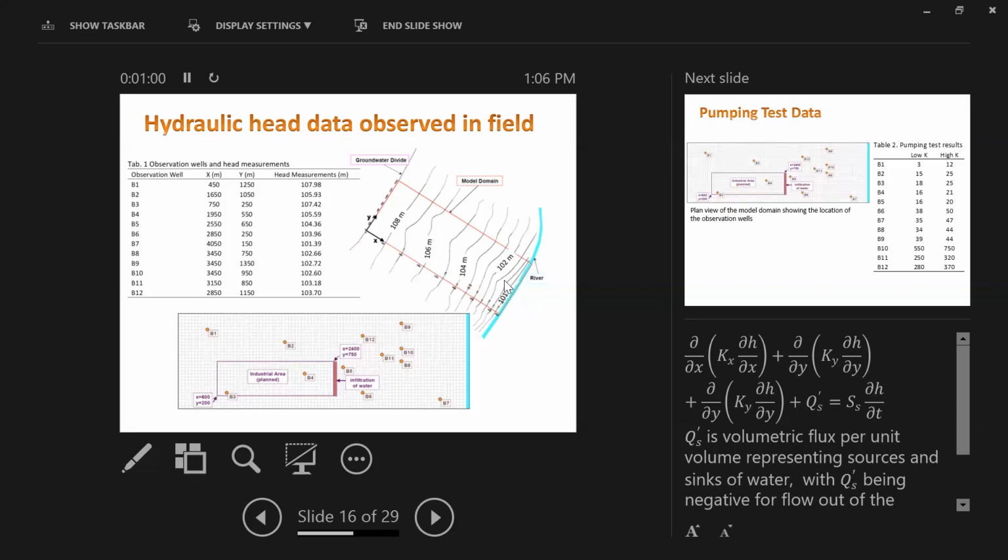And once you have the model purpose, then you put your governing equation, your mathematical model. So we have this simple mathematical model for our 2D aquifer, which has the hydraulic conductivity and the boundary conditions. This model solves for the groundwater head, given the definition of hydraulic conductivity and boundary conditions that you define, or general forcing and things that you have.